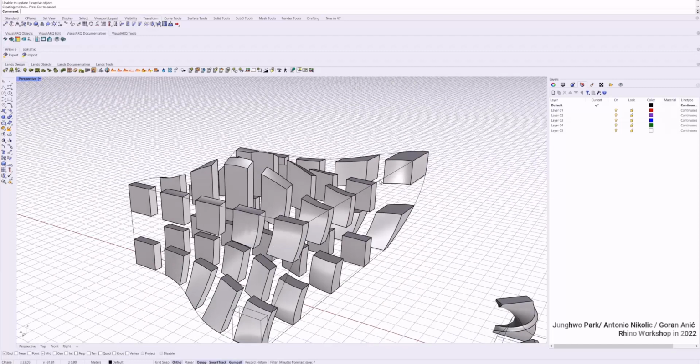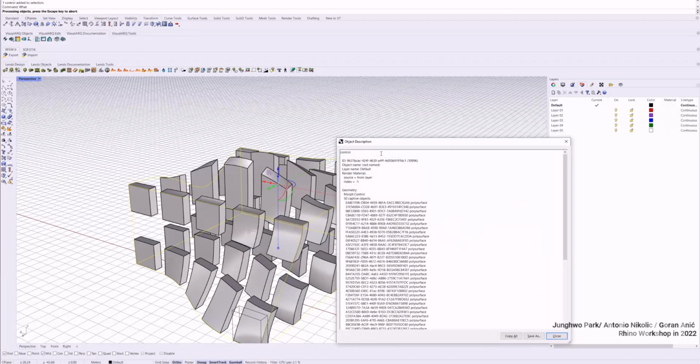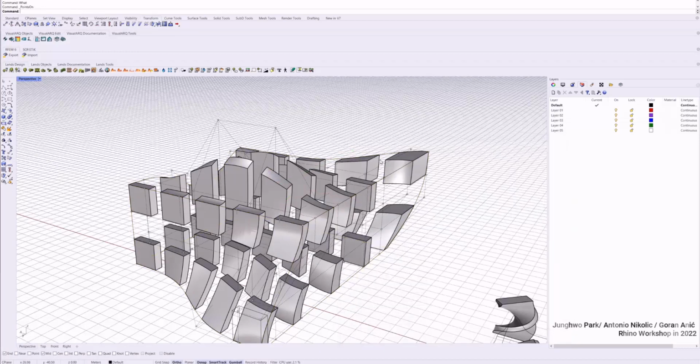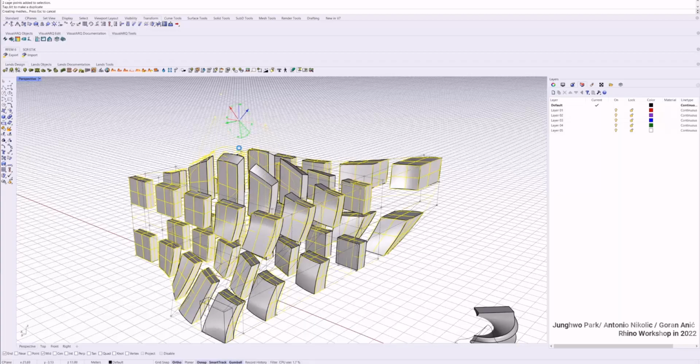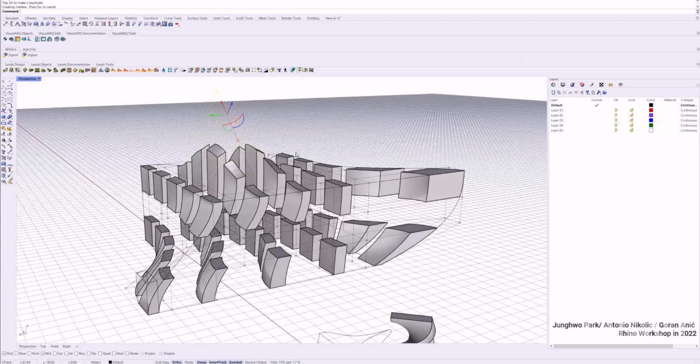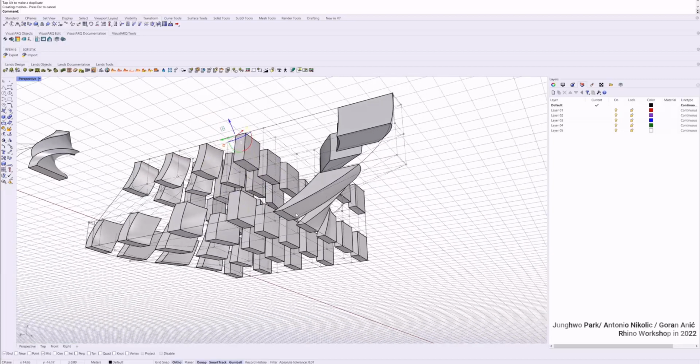When you finish, you can finish the command, and here you can always go back to this. When you type this, it is Control F. If you press F10, you can see the cage control points. You can show the control box points of the cage. You can also rotate it, of course. So accordingly, these are all changed.